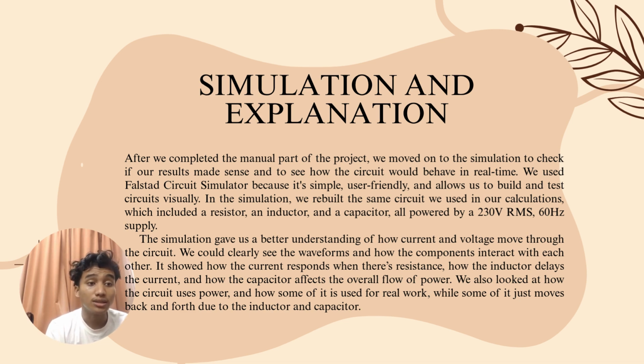This simulation gave us a better understanding of how current and voltage move through the circuit. We could clearly see the waveform and how the components interact with each other. It shows how the current responds when there is resistance, how the inductor delays the current, and how the capacitor affects the overall flow of power. We also look at how the circuit uses power and how some of it is used for real work, with some of it just moving back and forth due to the inductor and capacitor.